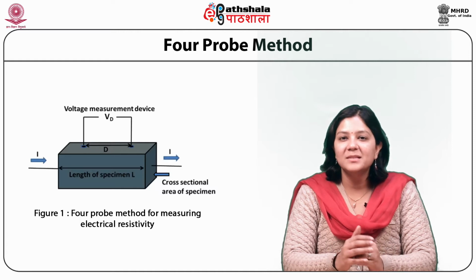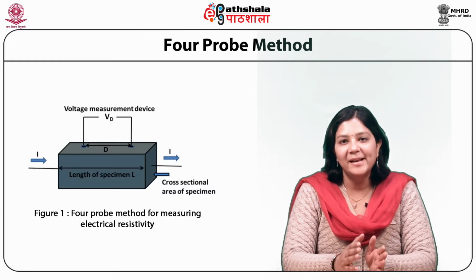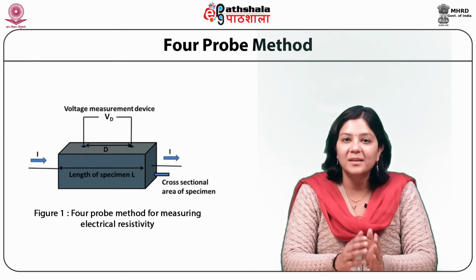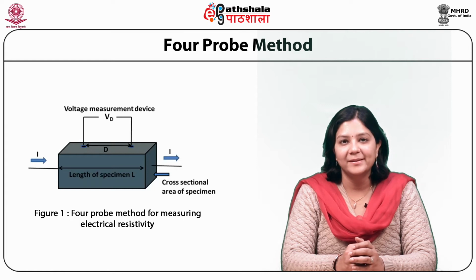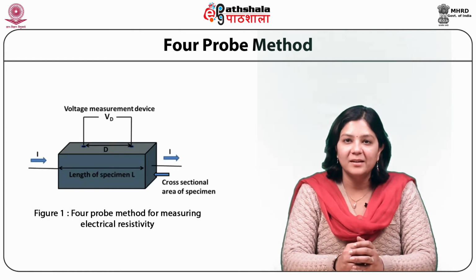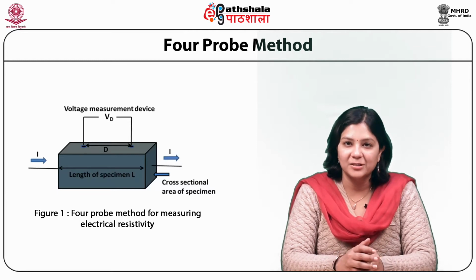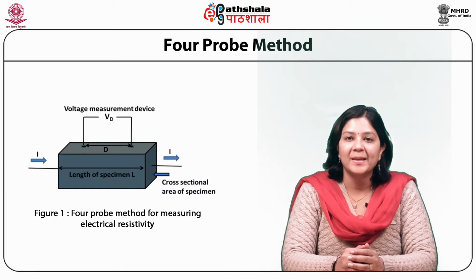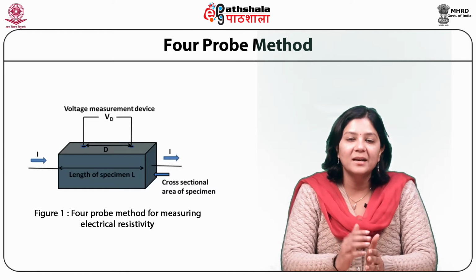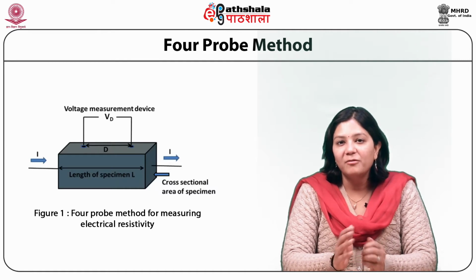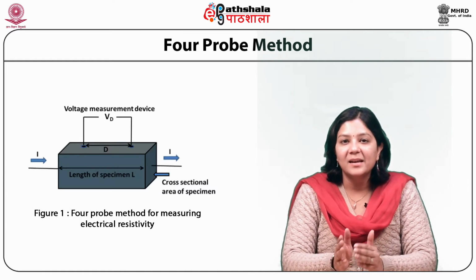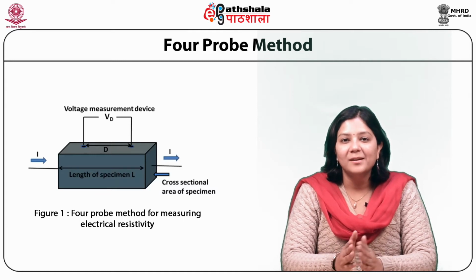Though the contact and the probe resistance themselves are cancelled out, there is still possibility of error in measurements if the contacts produce heat. Therefore, low resistance of contacts is preferable. The error due to DC offset in the instrument is readily overcome by subtraction. Additional self-induced voltage offsets within the circuit can increase the error. This may be rectified by flowing reverse current in the sample. A sample voltage of the order of a few microvolts might develop across the sample, thereby adding signal noise and increasing the error. This error can be reduced by shielding the cables, single point grounding, etc.